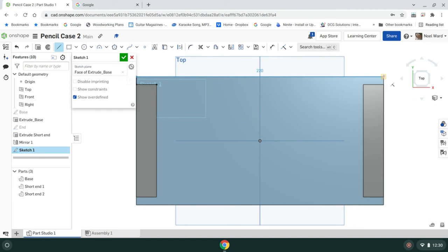You can see the dot is highlighted even though I'm further out from it, and it's highlighted again, and now that corner is highlighted. It's coincident. You see the little symbol? That's coincident with the line. So I'm going to take that there. It doesn't matter how far I come down on this at the moment. It's not level anymore, but when I go there, it's shown perpendicular to that surface, which is great. And then it's coincident with each of those. And that can be a wee bit tricky to do. So if anything goes off, you just click on it, delete it, and then go at it again.